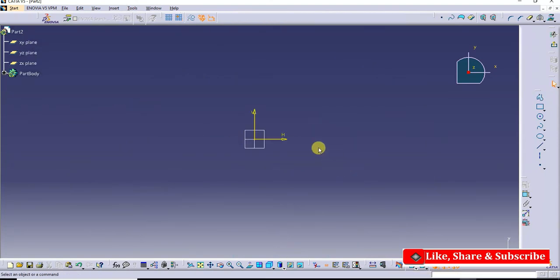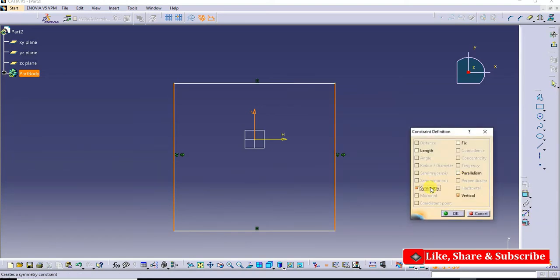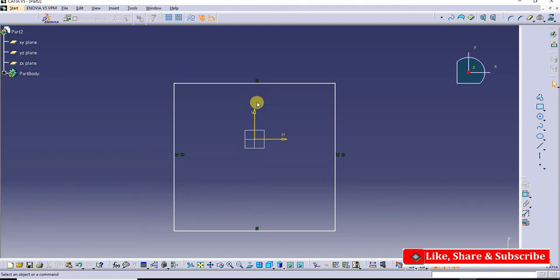Now, how to make the given sketch symmetric about either this axis or this axis? Let us see here. I'll take the rectangle command. I want this dimension to be symmetric about this axis. So what I do, I press the Control key on the keyboard, select this line and this. Next, the third one is the axis. Now this dimension will become symmetric about this axis. Now click on the constraint command, select the symmetry. Now this dimension has become symmetric about this axis.